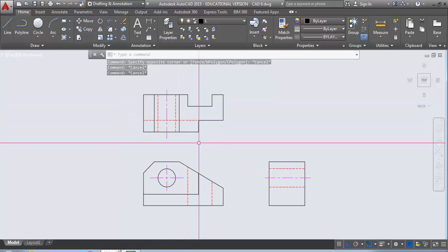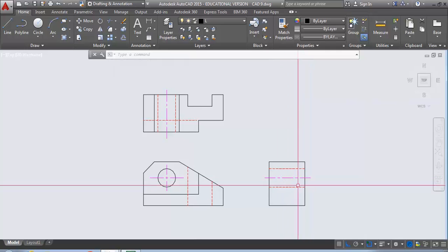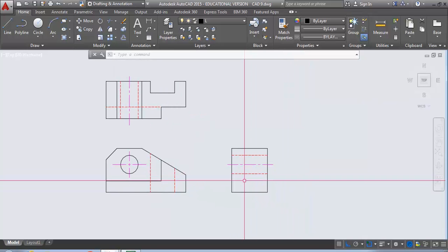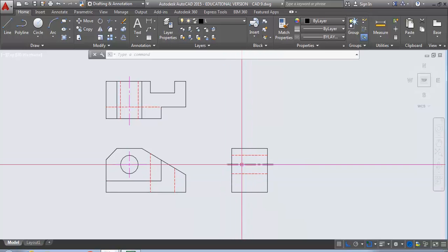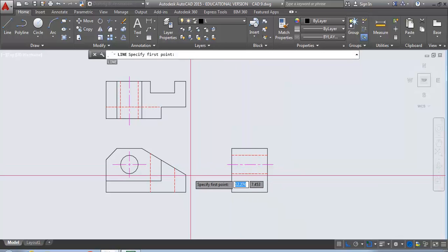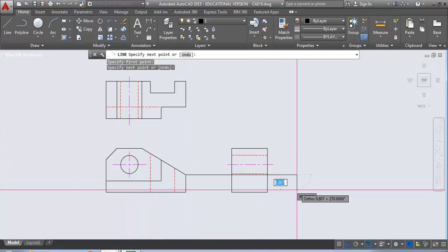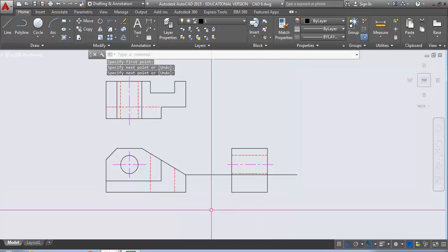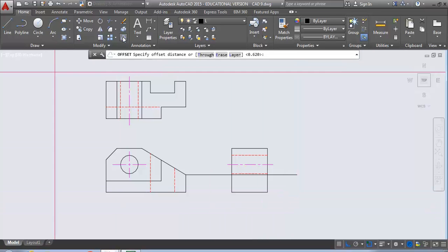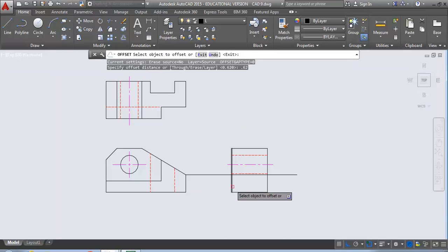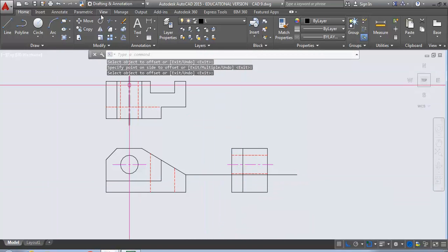So to finish CAD 9, here's my top view, front view. I started creating the right side view. And I just simply use offset and trim. I use them pretty much all the time. So let's go through that and develop this right side view. So I'm going to draw a line from that endpoint. I'll go up here and use the line, draw a line from here, bring it across, and that is 0.62, so I'll go to offset, 0.62 back, say that goes back here, and then I can trim, use the trim function,